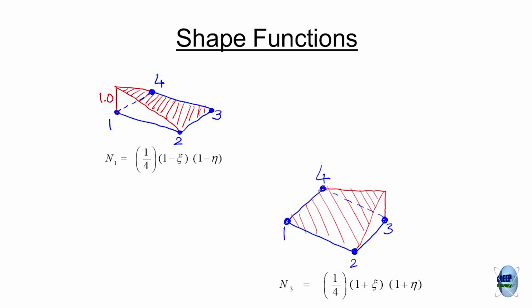What we have drawn here on the blackboard with the linear shape functions for one dimensional analysis, it goes from 1 to 0 at the other node. Here it would be 1 to 0 at the other two nodes also. Node 1, it is 1; 2, 3, 4, it has to be 0. So, it is that bilinear function f of zeta eta, which would be 0.